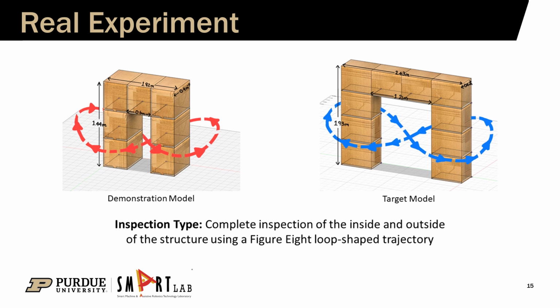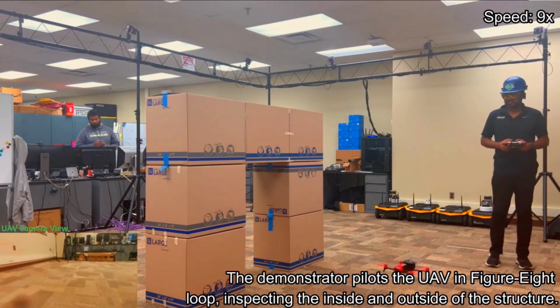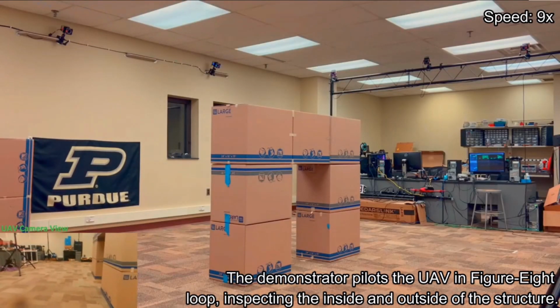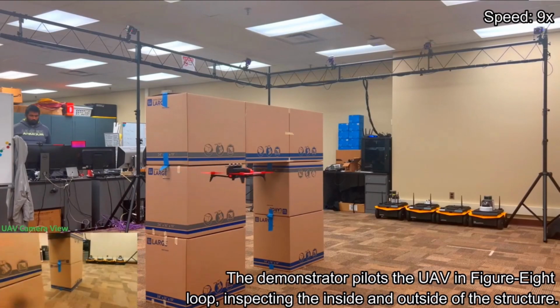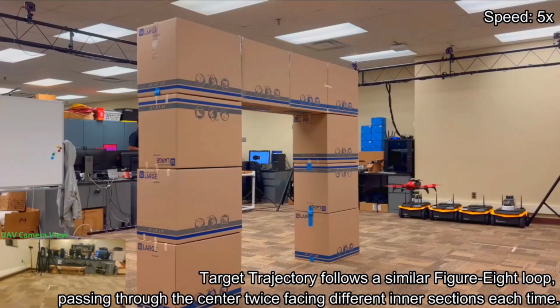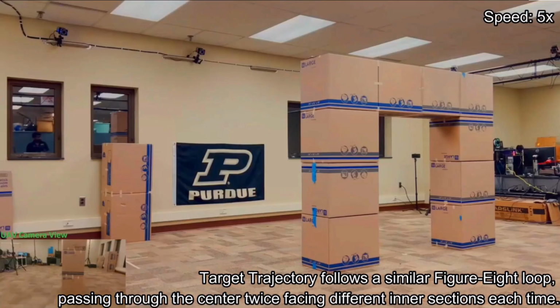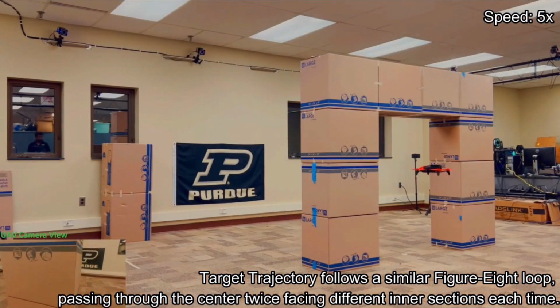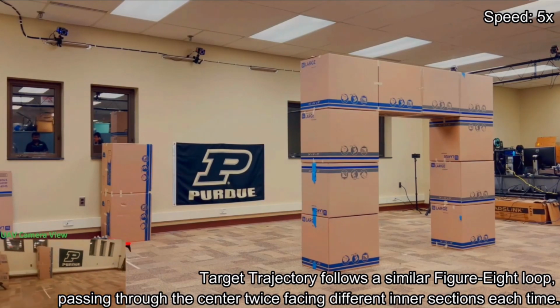We also validate the method in the real world. We use a bridge-like structure and an 8-like trajectory to inspect the columns of the structure. Here, the expert UAV pilot flies in an 8-like path around the structure and inspects the columns of the bridge. Following this, a target trajectory was generated, and the UAV flies autonomously in an 8-shaped path across the columns of a bridge-like structure, inspecting it pretty similar to the demonstrated one.